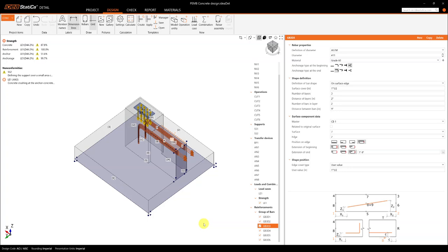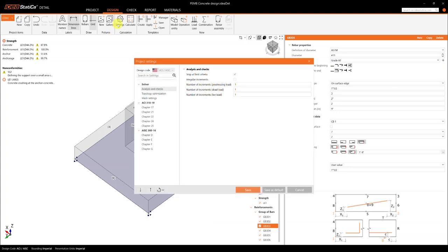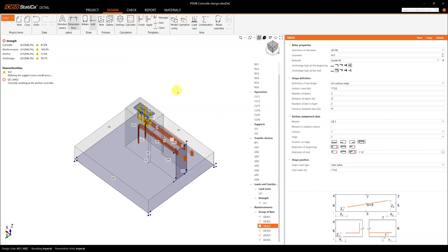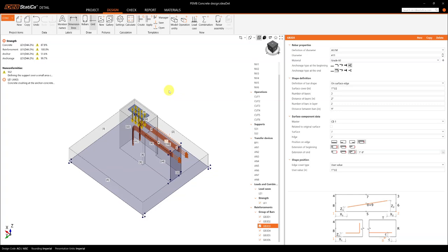All right. Now, the trick that I use here to have a faster analysis is that I change this mesh setting to have a default mesh size of 5. So this is a multiplier only. This will increase the size of the elements of this 3D FEA block mesh size. Okay, so this is just to speed the analysis. So in an initial calculation, you don't have to wait too much for the results. So after I click calculate, this is the result I got.